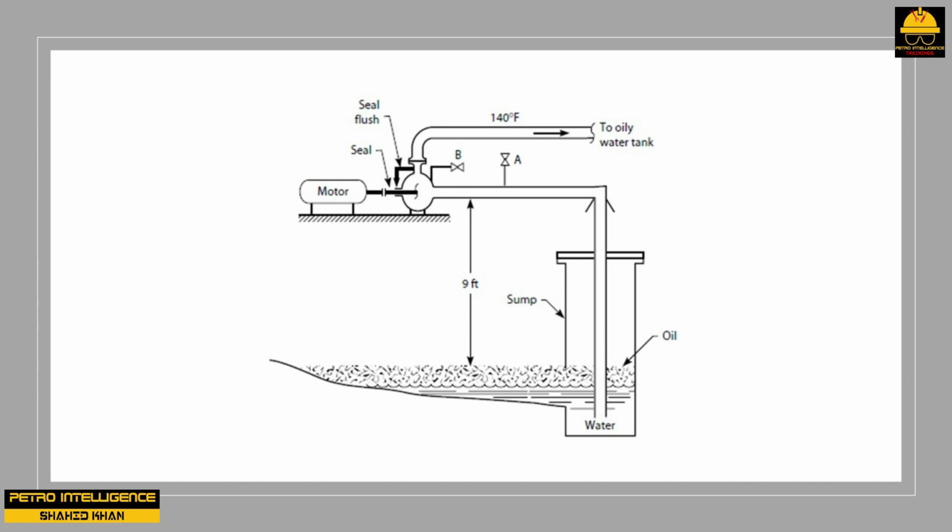This air displaces the water in the pump's case and, with time, causes the pump to lose its prime. To fix this problem in the refinery, the engineer connected an external source of seal flush water to the pump from a nearby wash water station. Pumps that have subatmospheric suction pressures, and that are not in continuous service, should not be self-flushed pumps. They should have an external source of seal flush material connected to the mechanical seal. With the external source of seal flush, the pump no longer lost its prime when shut down.